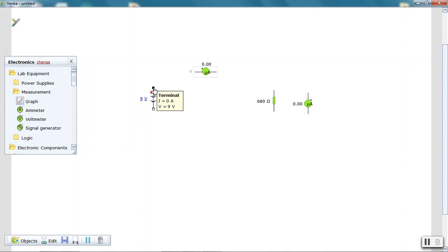And the proper way of an ammeter, again, is you hook up the wire to one end and hook up the other end to where the current is going. So the proper way is the current is forced to go through the meter, and the meter measures the current going through it. And then on the other end, complete the circuit. So all the current is forced to go through the meter, and the meter measures the current through it. This would be what's called a series arrangement. The meter is in series with the resistor. The current goes through here, and then all goes through here.